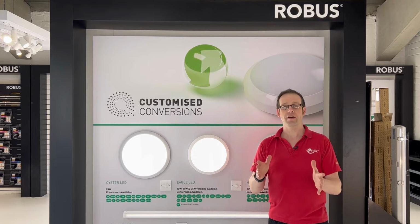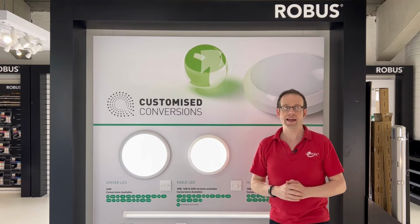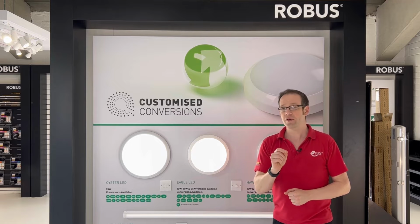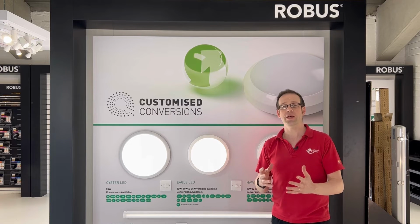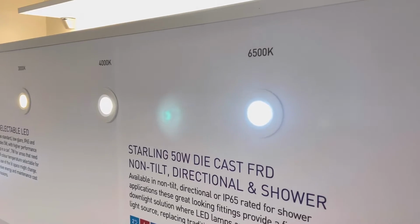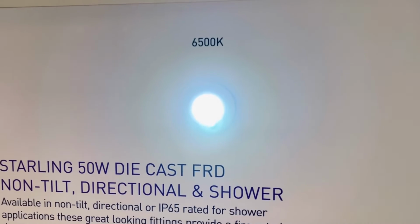After all, if you stand directly under a light fitting and stare directly up at it, you're going to get glare. What this rating means is that the light has been designed so that if used in the correct application at typical heights and spacings, it will help the lighting designer to achieve a UGR of less than 19. Again, if you install a low glare fitting pointing directly out of a wall at eye height, it will create a high value of glare, as this is not the intended use of that fitting.